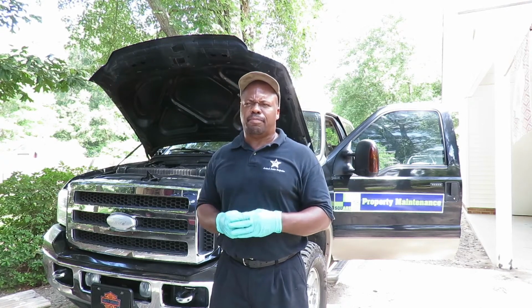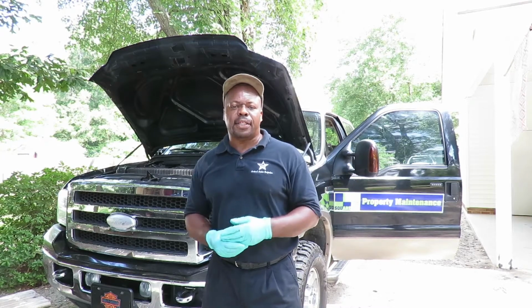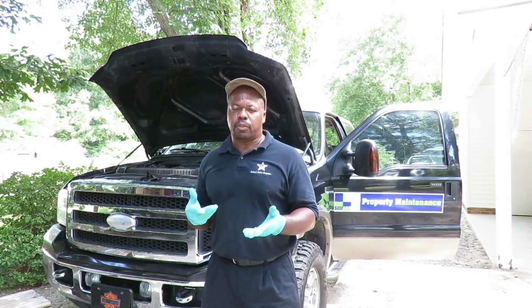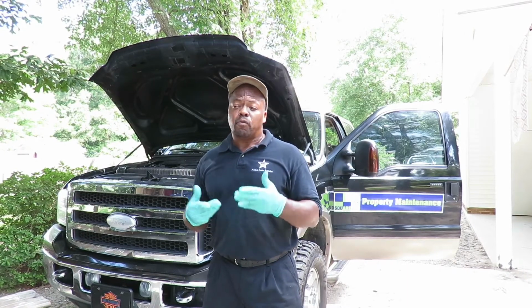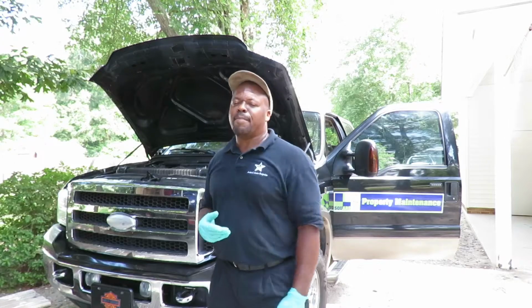And usually what causes that is a throttle body needing cleaning. A lot of carbon builds up around the blade, which I'm about to pull this air cleaner off and show you. Or on rare occasions it could be the throttle body itself. So let's get on the Actron, and I'm going to show you what that means. Be right back.